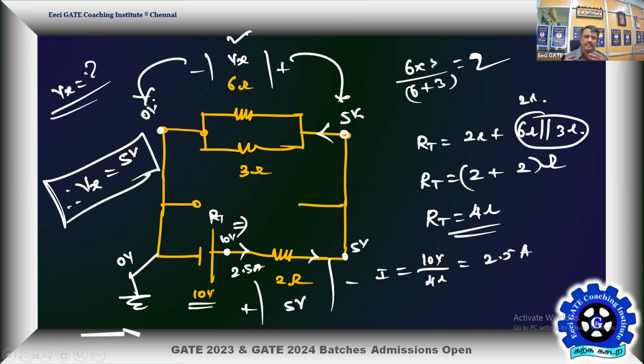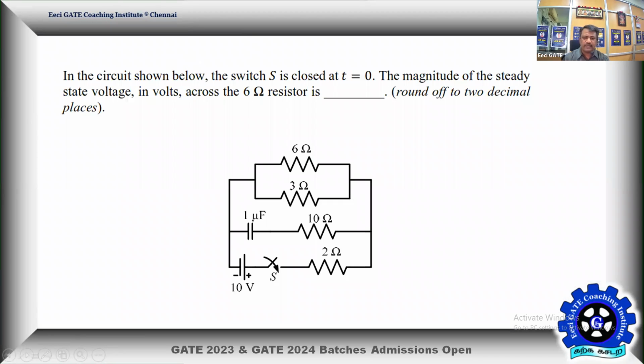Okay, so there is nothing to play in transient, because although the transient circuit is given, the problem is set in steady state. That means all the transients have already died out at steady state and the capacitor branch does not come into play. That current being 0 is the key to get the answer instantly. That's how this problem has to be approached. That's one of the interesting problems from the electrical GATE 22 paper.